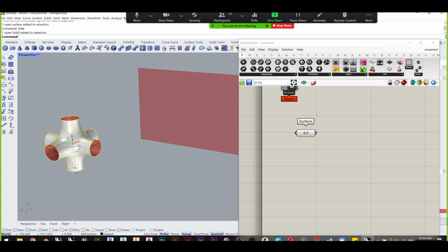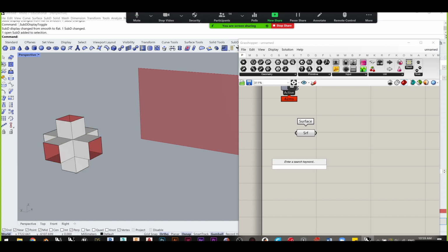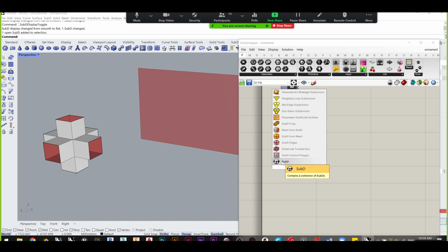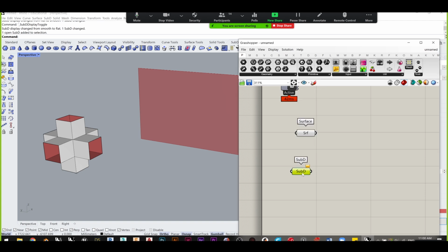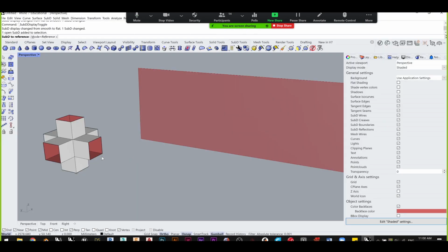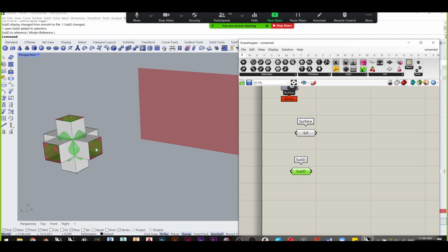And we will do the same thing with this SubD geometry, right? So I need to link in the SubD geometry. I can do that by creating a SubD node, again, that black hexagon. Right clicking on it and choosing set one SubD and choosing my SubD here.